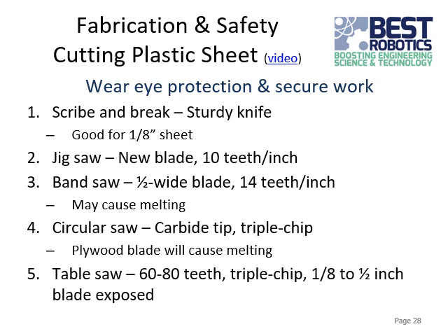One thing I want to tell you right up front, and that you'll probably hear me say quite a few times, is make sure you're wearing eye protection. Plastic especially can chip or melt and have little melty bits of plastic fly out while you're cutting it. All that stuff is really bad, you don't want it in your eyes. So always wear eye protection when you're cutting things or working with power tools or anything like that.